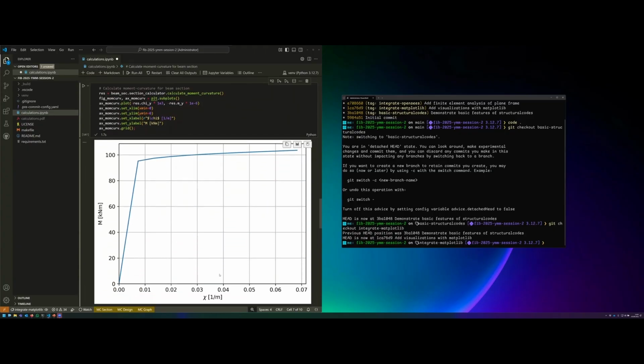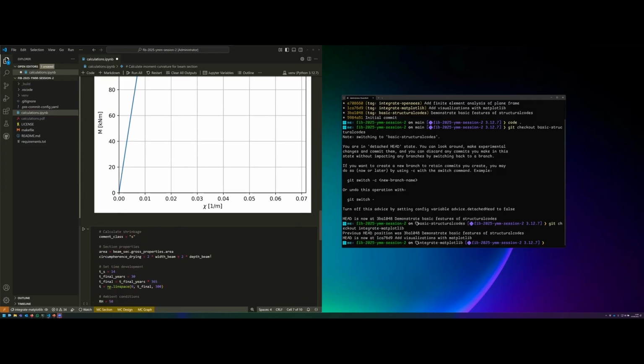So now you have the moment and you have the curvature, and you see this is a typically under-reinforced cross-section where you have the distinct yield point and the ultimate point over here to the right. Since we have no tensile capacity defined in these constitutive laws, we are directly along a cracked stiffness, or say a cracked behavior, of the cross section.